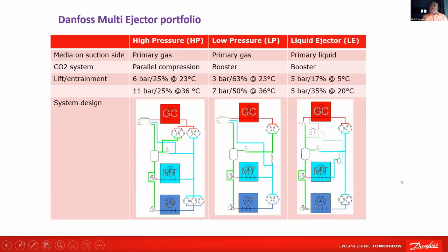And the next one, last one, is liquid ejector. Liquid means you run the MT evaporator with a very low superheat such that it runs almost flooded operation. Means you are not controlling superheat anymore. So that will leak out some liquid from the evaporator. Therefore, the efficiency of the evaporator is much higher. And with CO2, yesterday Professor Pramod was saying, the theoretical efficiencies are very close to actual efficiencies. So with liquid in, the efficiency is even higher.